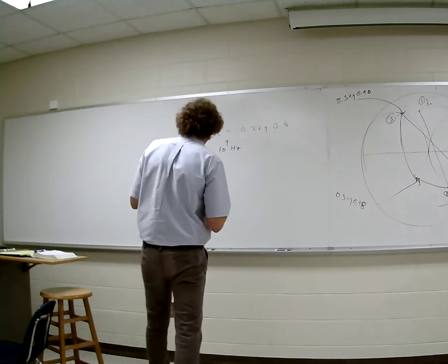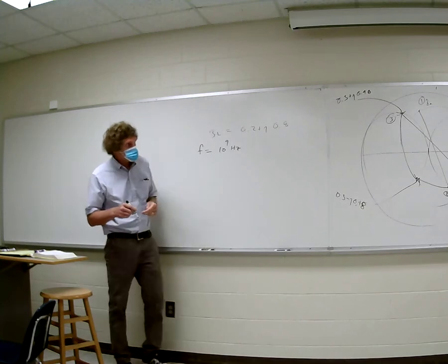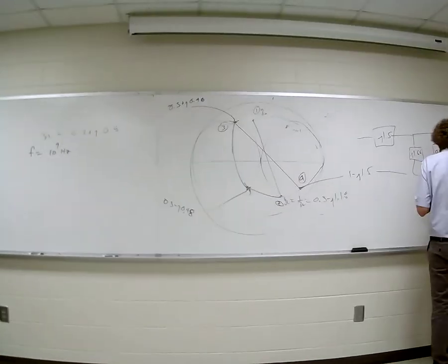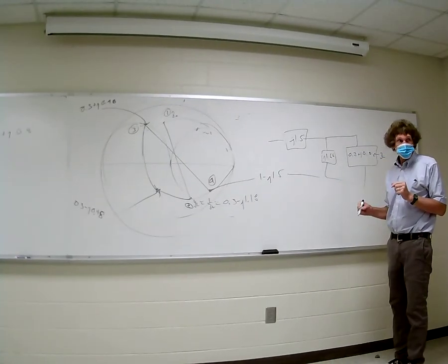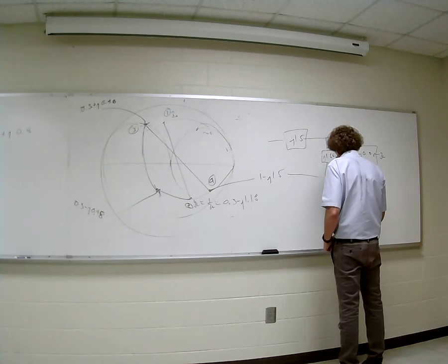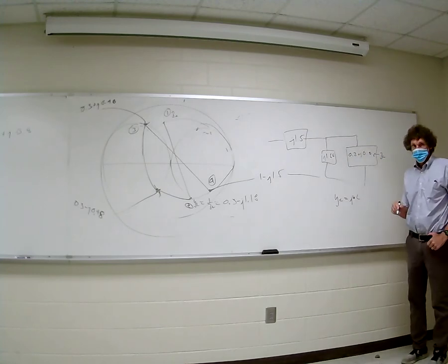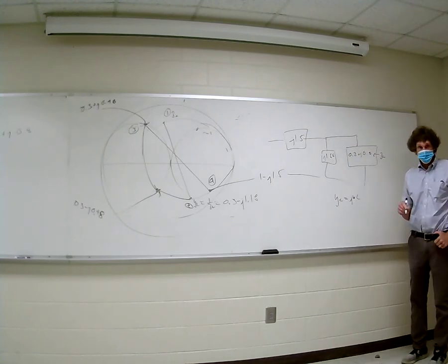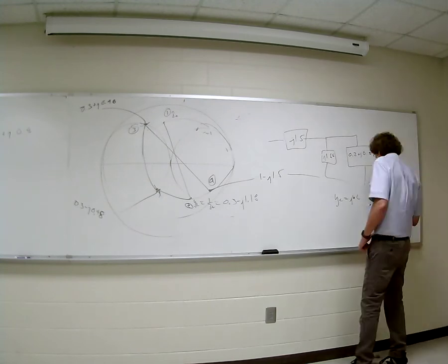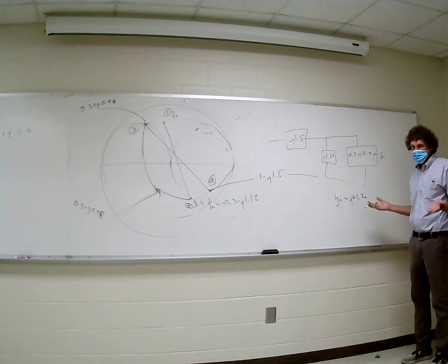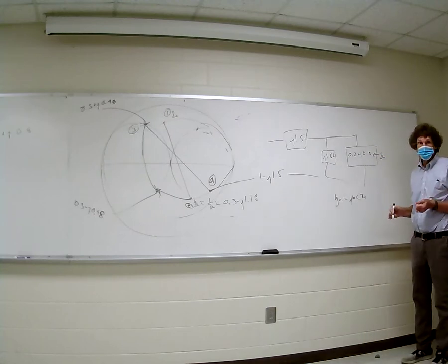All right, so if f is 10 to the 9th hertz, now let's get the actual elements. Let's go ahead and get this one first. That's admittance normalized. We know it's a capacitor, right? So in general, the admittance of a capacitor is 1 over the impedance, so it's just j omega C, right? That's the admittance, correct? And if it's normalized, we multiply by Z naught. You can just get the normalized impedance, 1 over j omega C divided by Z naught, and then take 1 over that. That's the normalized admittance. Everybody okay? All right, we have that.